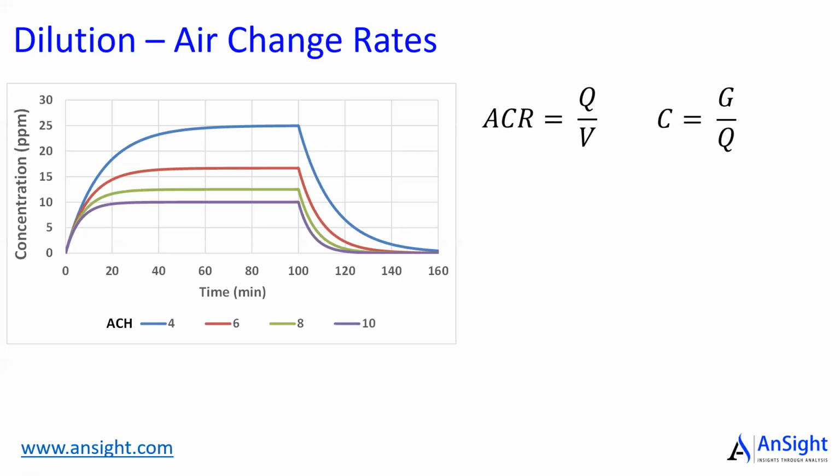Most of the time, people think air change rate is like how many times the room is exchanging the air with outside. It doesn't work like that. It's not a piston effect, like you just push the air in one direction. Once the air comes in, it circulates in the room, probably stays a little longer, and then leaves the room eventually. But it is not necessarily a very linear exchange of the outside air with the room air. Now, how to determine the dilution concentration? Very simple equation.